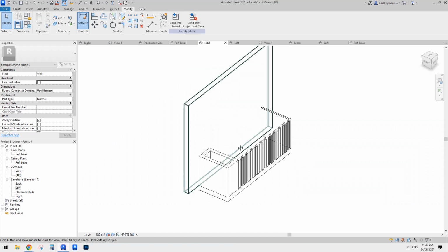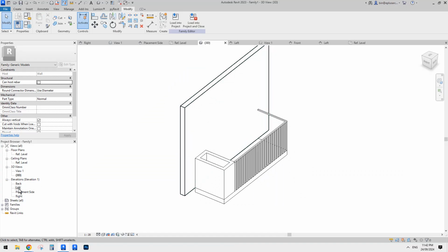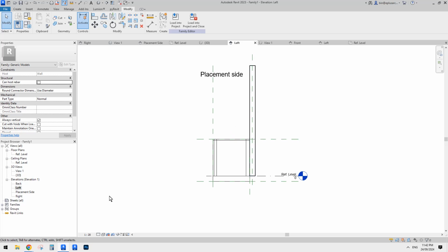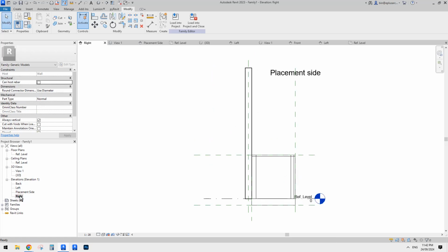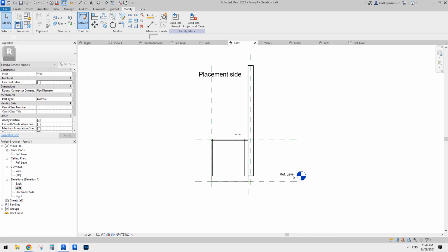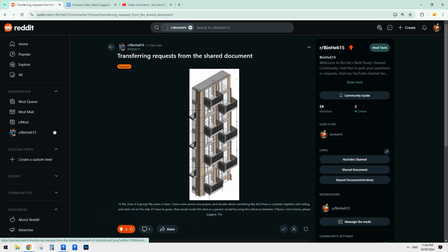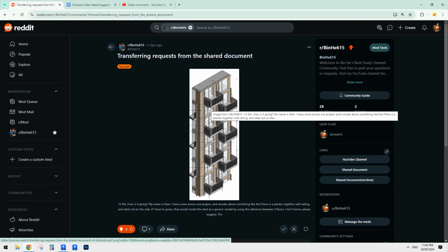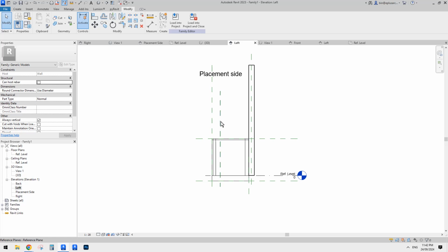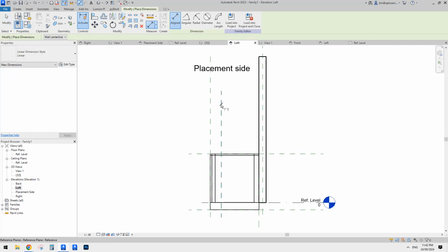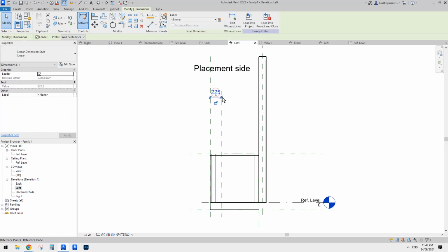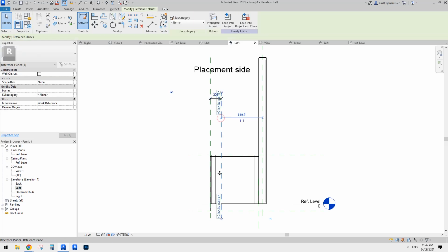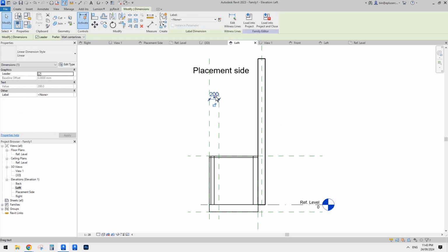Let's do it. Sorry. I think we should probably just add into it. So this is a left, okay, so this is a right, okay, so left. We just add a reference plane here. So let's have a look again. You can see fix here. This is one option, another option is just vertical, right? So for this option, we can just add a dimension here, and then you can adjust this number as an offset from the edge of this. So you can create a parameter.